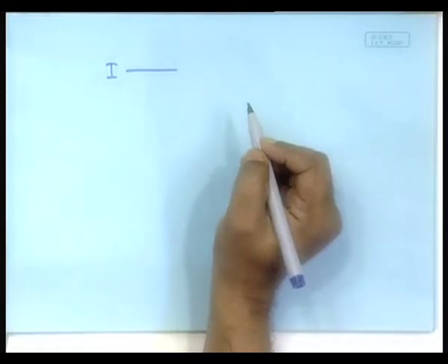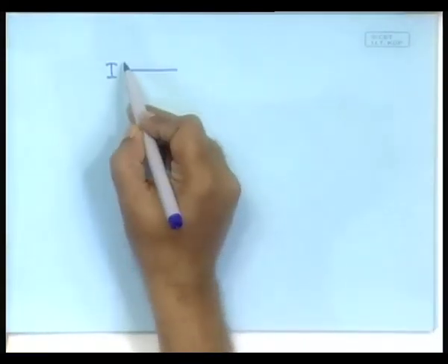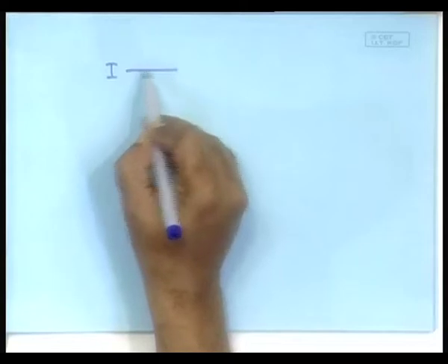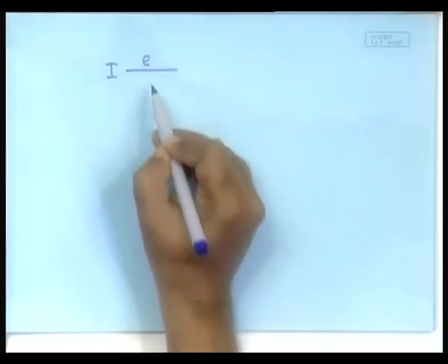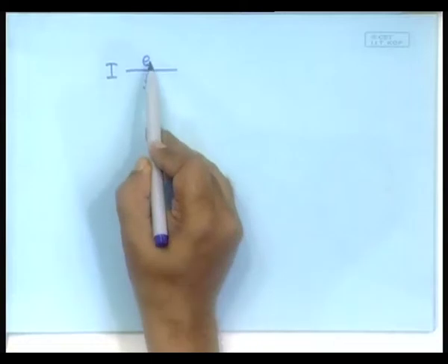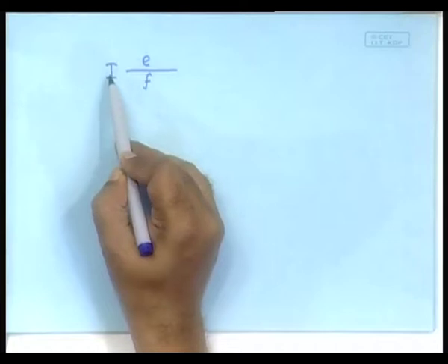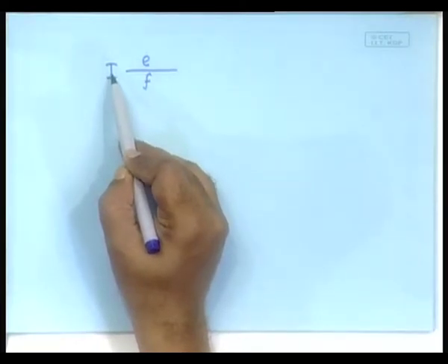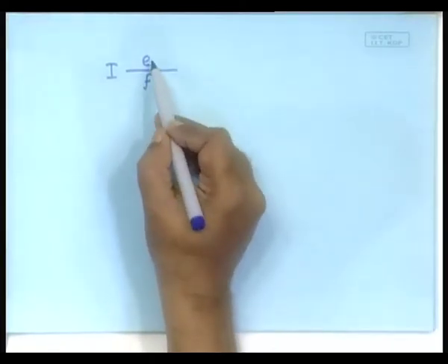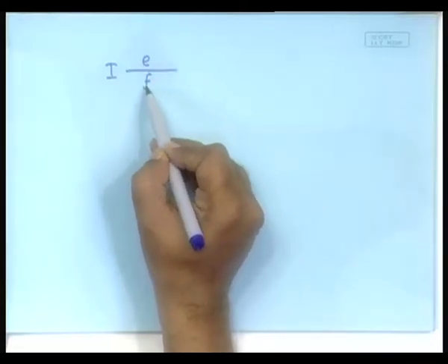So far we were considering the R element, C element, I element as a one port element, connected to the rest of the system. What does it mean? It means that here is, say, bond number 1, with an E flowing and an F flowing. Then this E and F completely determine the characteristic of the I element, which means its effort is completely given by the history of its flow.